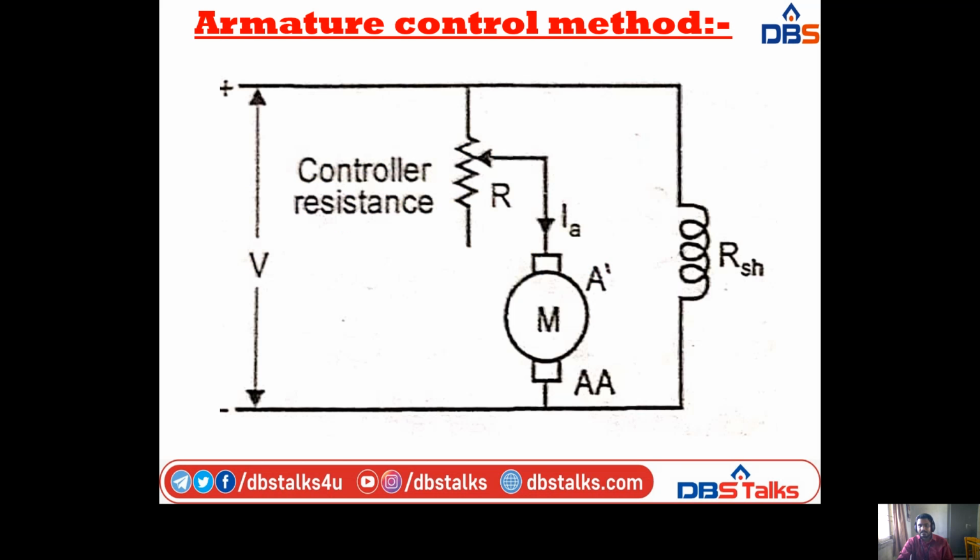This is the diagram for the armature control method. In this diagram, the motor consists of an armature winding and a field winding. Here the armature winding is in series with the controller resistance R, also known as a rheostat. Next we have the parallel connection of the shunt field winding, and these are connected across the voltage V.